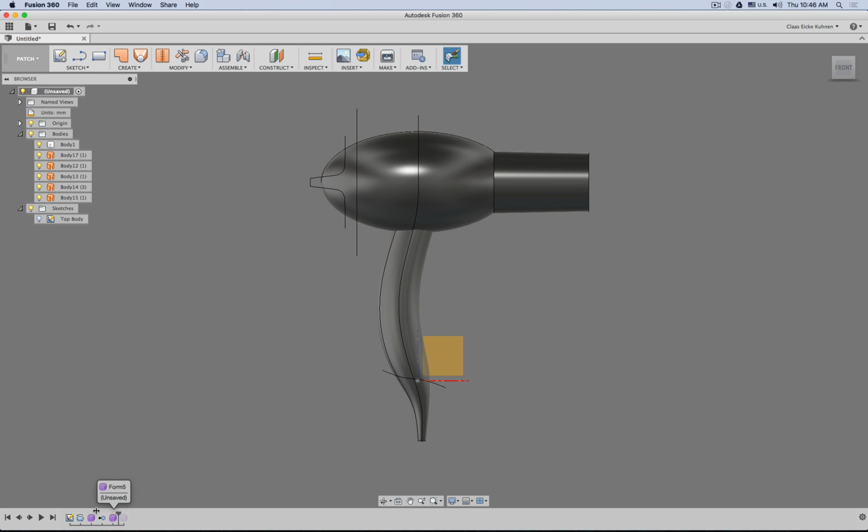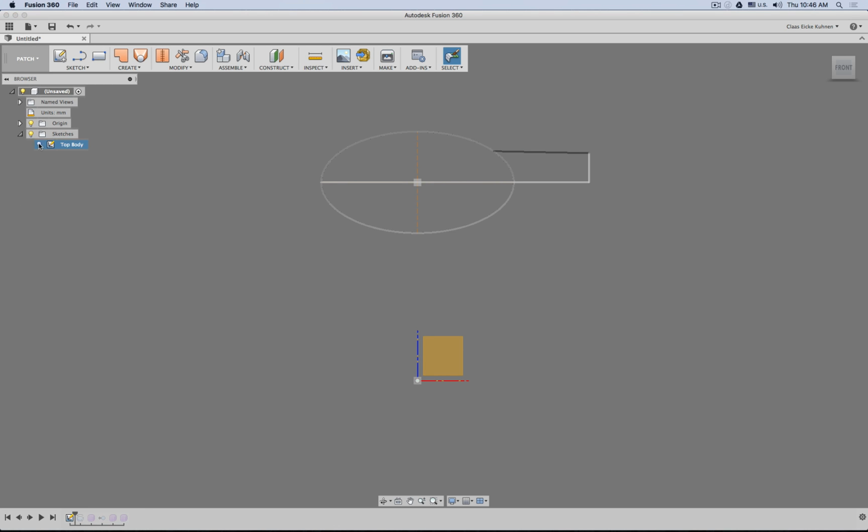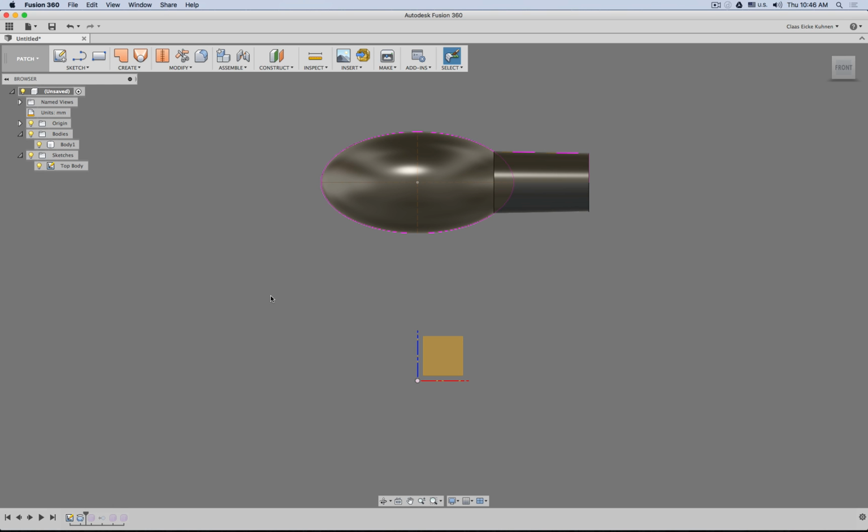Let's go to the timeline. I started with a very basic sketch, an ellipse, and then this area for the exhaust. I want to have a very nice elliptical shape. So ideally, because this is a perfect geometry, we don't want to do this with sub D or T-splines. Here we use a sketch ellipse tool, and then you see I created a revolve object.